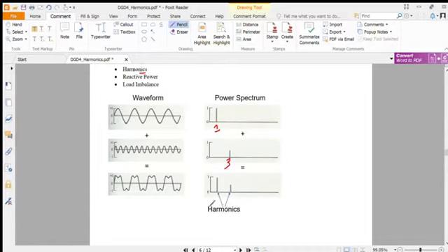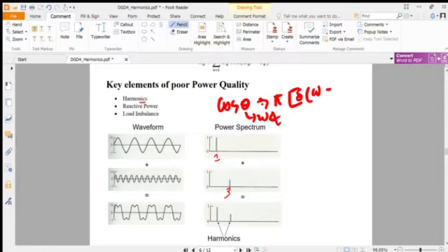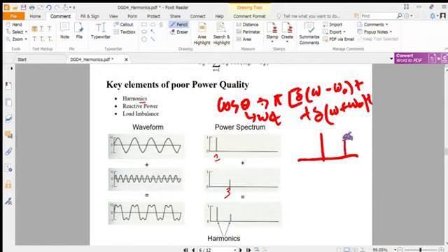If we add, it's just like a spike, because we know the Fourier transform of cos θ, where theta is actually ωt, is π[δ(ω − ω0) + δ(ω + ω0)]. So if we draw the spectrum, this is ω0 and this is minus ω0, and the amplitude is π.